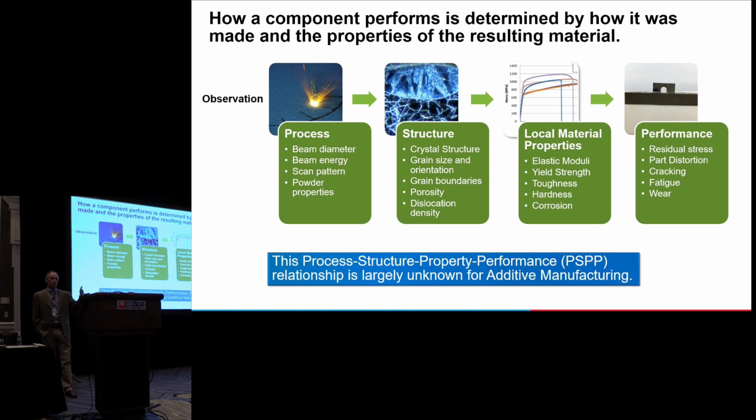So keep in mind that the desired properties are dependent on your application. So you may need different materials, different processing parameters, and there's always trade-offs economically between how fast can I turn out a part. If I have more time to spend, maybe I can preheat the box and/or do a post heat treatment afterwards and alter the grain structure that way. So all of these things come into play.